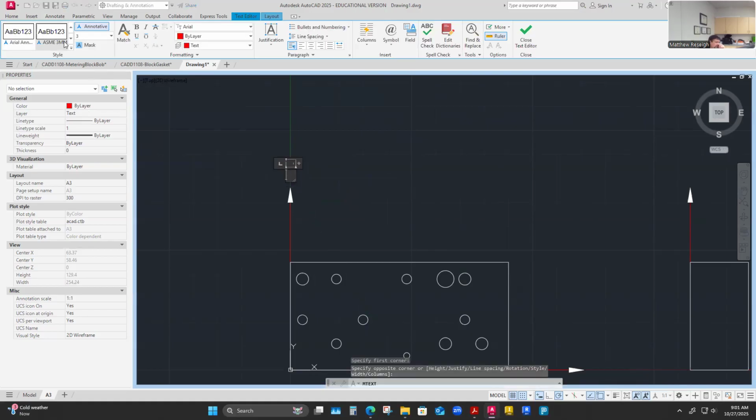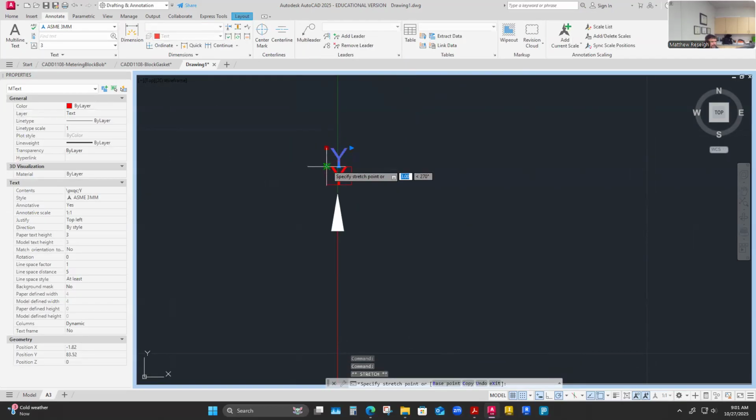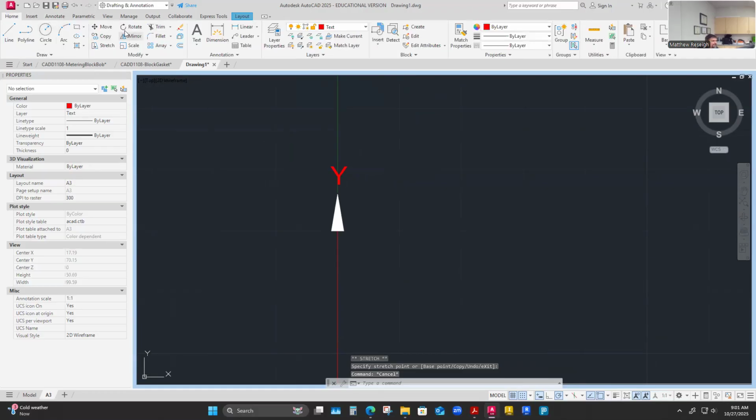Make sure that I'm using, I think for this I just use my normal 3 millimeter. With a section plane and a section view, I would definitely use double the size. Here I'm in that ambiguous area. Maybe I don't even need this big of an arrow either, and maybe the text size is a little ambiguous. So I used my 3 millimeter text size to say that this is Y, capital Y. Maybe I've center justified, but that's about it. Pretty simple label there. Copy this over.